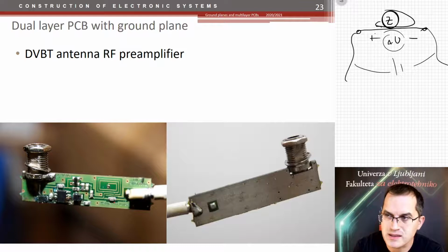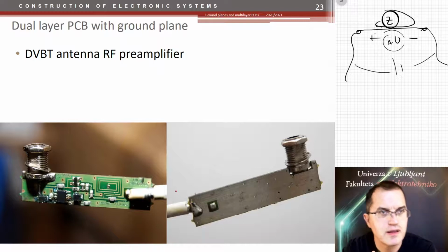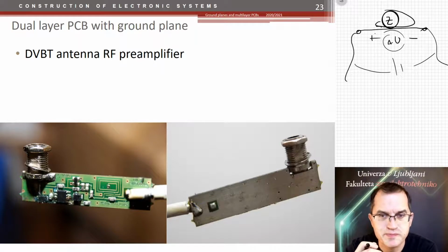And that impedance is required to have a maximal energy transfer from input to output, due to the rule which says the impedances should match, and therefore you would get a good transfer of energy. If the impedances do not match, then you have reflections, and these reflections would cause problems.